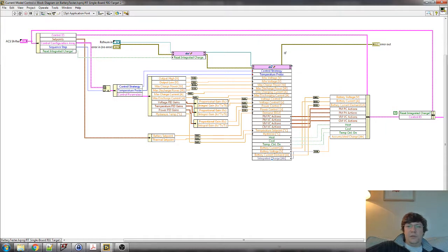I'm pushing it into our FPGA and reading back our current and voltage and so forth, and our integrated charge as well. Integrated charge set up to be calculated on the FPGA is the only surefire way I've found of not accumulating the loss or gaining of a coulomb now and then over the course of a number of months.